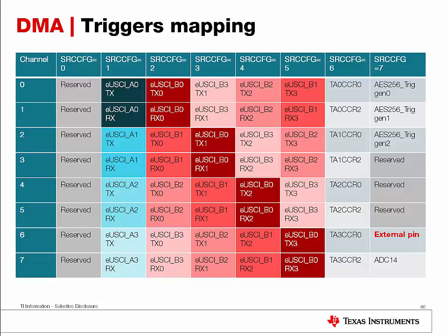For example, you can configure the ADC to sample a signal from an ADC channel, and when that conversion is finished, the DMA can take the value from the ADC memory results over to the SPI transmit buffer. Vice versa, you can also configure the DMA to receive the data from an I2C receive buffer and transfer that directly to memory. So with that, we have concluded part 5 of the MSP432 MCU training series, where we have